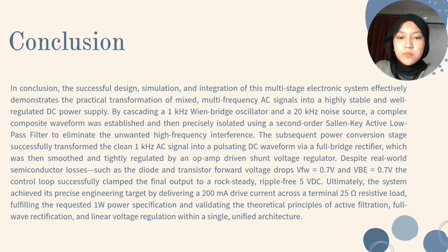Finally, to conclude the presentation based on the summary, we have successfully designed, simulated, and integrated a multi-stage electronic system that effectively transforms a mixed AC signal into a stable DC power supply. To summarize our process, we established a complex composite waveform using a 1 kHz Wien bridge oscillator and a 20 kHz noise source. A second-order Sallen-Key active low-pass filter was used to precisely isolate the 1 kHz signal.